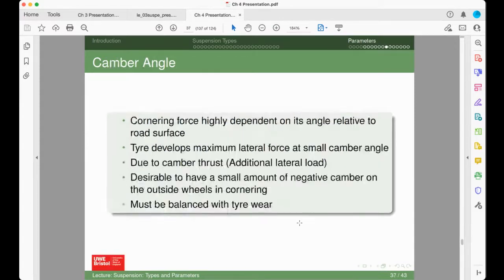The other aspect of negative camber, and we'll cover this more next week, is that if you set a vehicle up with negative camber in the first place, as the vehicle body rolls in the corner, that negative camber can accommodate that roll and still end up with either zero camber or a little bit of negative camber as the vehicle body rolls. So like I said, you need to camber the wheels slightly in.